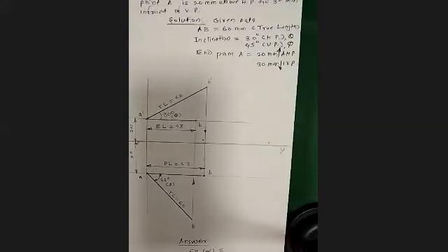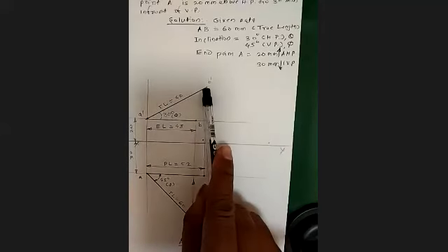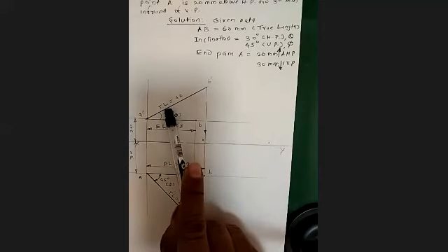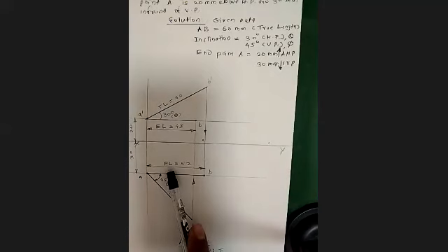so for this true length in front view, that is the line inclined to HP, you are getting a top view and that AB here, okay, and the distance from A to B is nothing but your top view length, or alternately we can say it's a plan length, and in short we'll write it as PL.